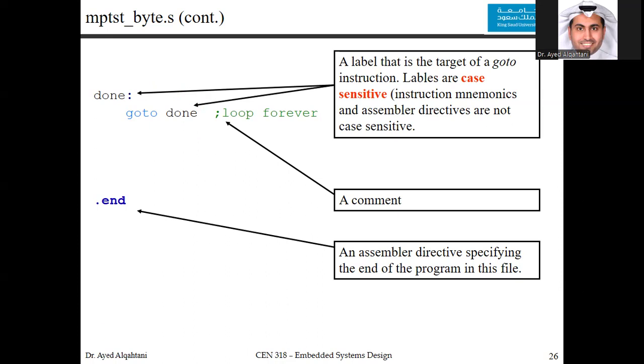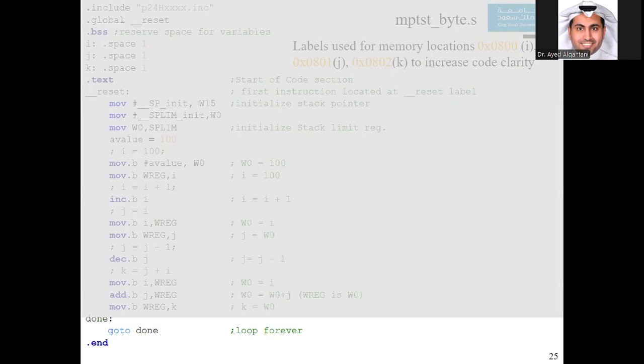Once you finish your code here, if you don't have this infinite loop, it will go out and the microcontroller will not do anything to your subsystem. To make sure that the microcontroller is still alive, at the end you should make it stuck in an infinite loop. Okay.